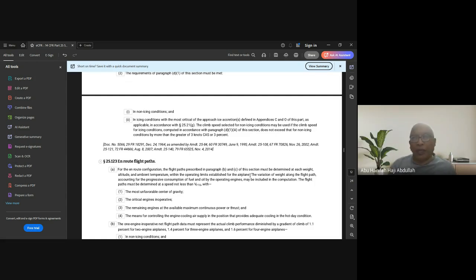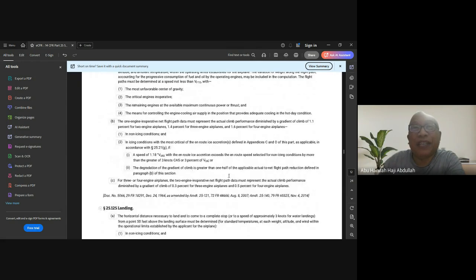When you design an aeroplane, we also need to think of the cost: operating cost, acquisition cost, the buying price of the aeroplane. We need to balance between cost, operation, and safety. Otherwise, if everything is two-engine, and you just want to fly Ipoh to Kuala Lumpur, for example, then that's why the Cessna Caravan is a single engine and can operate commercially.